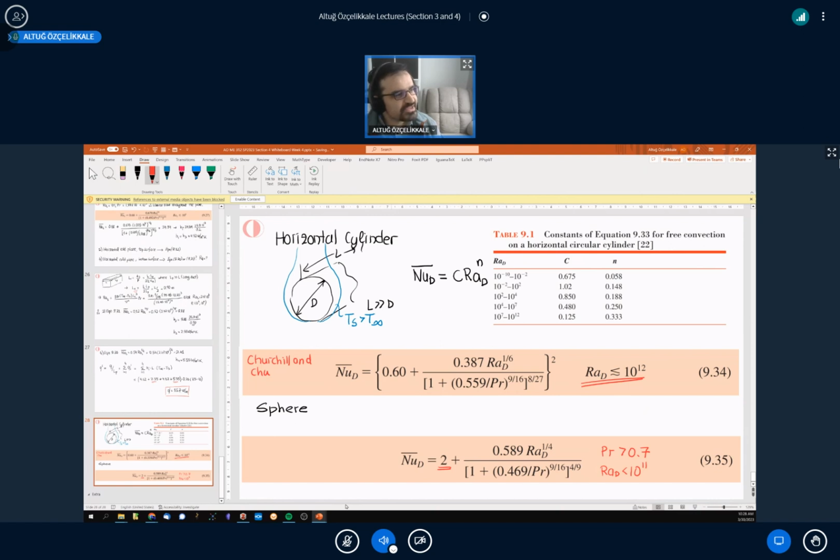Remember 2D conduction, chapter 4, the shape factors. You can go to the table and find the associated shape factor, and that's essentially the condition when the fluid is stagnant, right? So that's the baseline where we are going to have heat transfer by conduction only, and that sphere in a stagnant infinite medium will give us a Nusselt number equal to 2. You can go back and trace that.